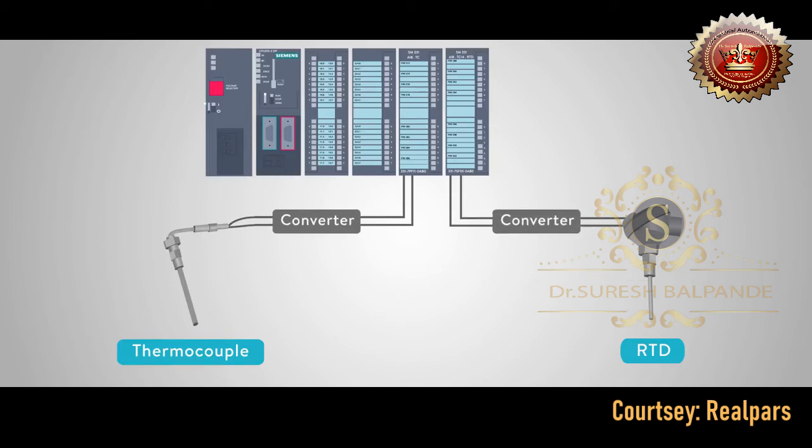The most commonly used standard today is the 4 to 20 milliamp signal because of noise immunity and other characteristics. And every type of analog sensor I have mentioned can generally be purchased in that type of output.